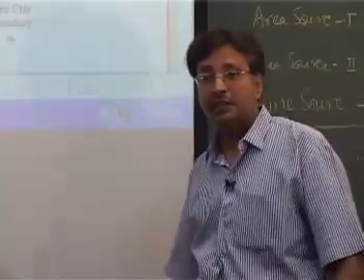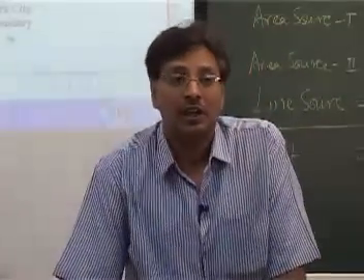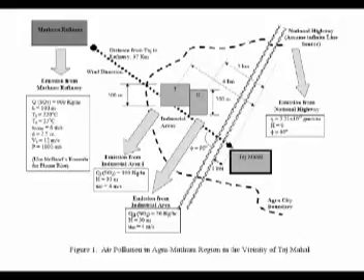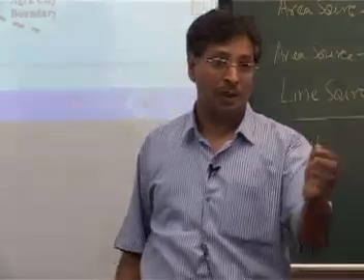So one of the other ways to do it is to use a tracer gas. Along with the emissions here, you release a tracer gas from the refinery. And you release another tracer gas, or the same tracer gas, at some other time from these other sources. And they measure the tracer gas, because the tracer gas will not be contributed by anybody else. So then you can really establish how much is the contribution in measurement terms.